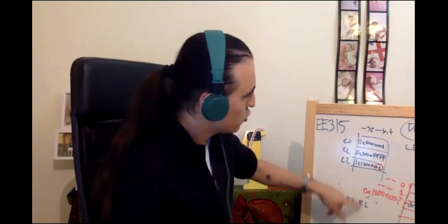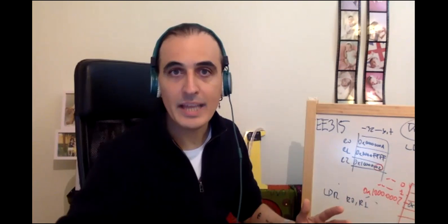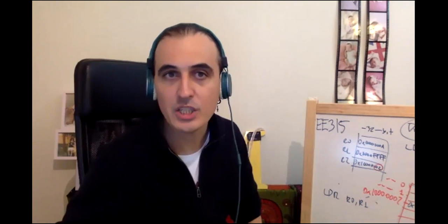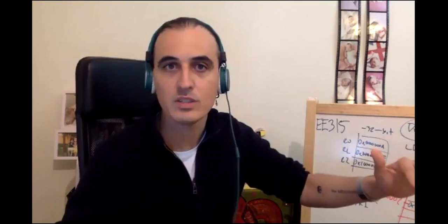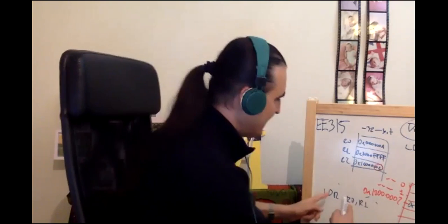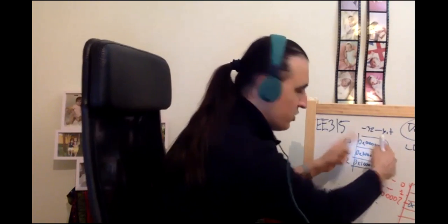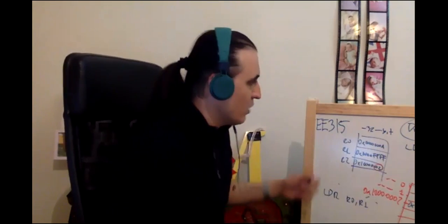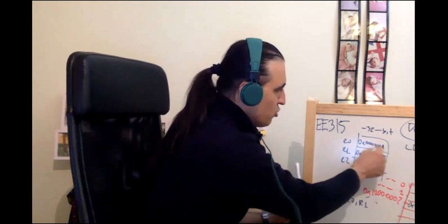So I'm writing this value over here. LDR was a 32-bit operation. It reads a 32-bit value from memory to register, register to memory, or register to register. However, move is 8 bits. Since LDR is 32 bits, I'm getting it all and overwriting it. If this operation was executed, I would have deleted this one and put all 000 FF.